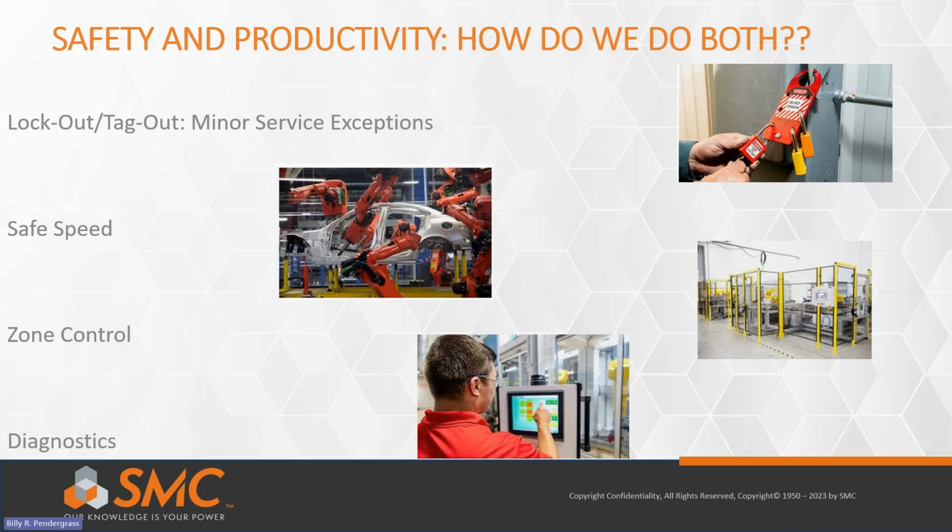Controlled from a safety PLC, distributed safety I/O modules can be located on the machinery close to sensors and actuators. These modules do more than ensure safety functions are operating correctly. They also pinpoint the source of a stoppage on your safety system and more quickly guide technicians to an effective restart.